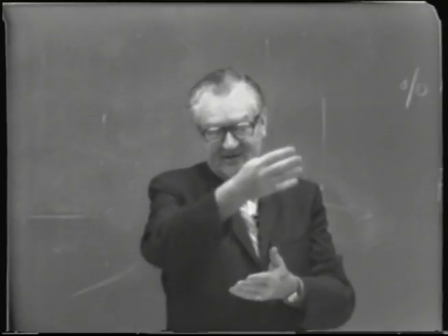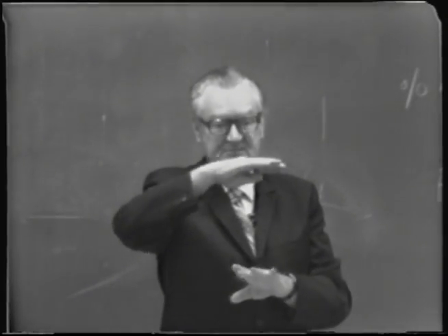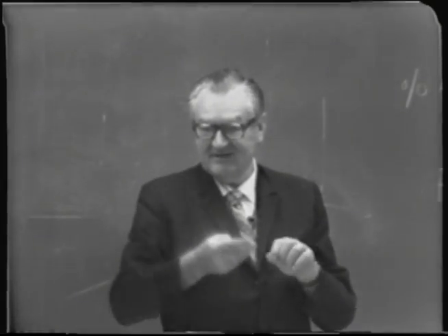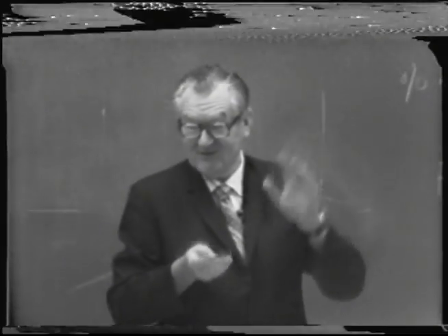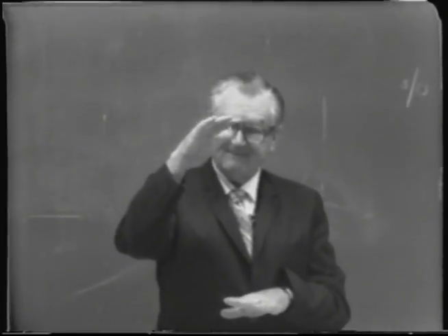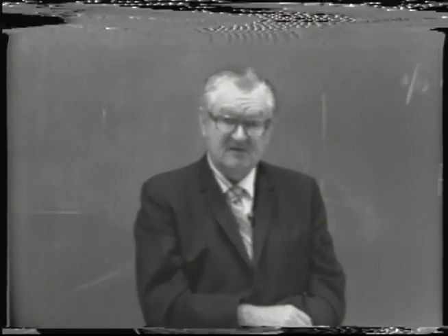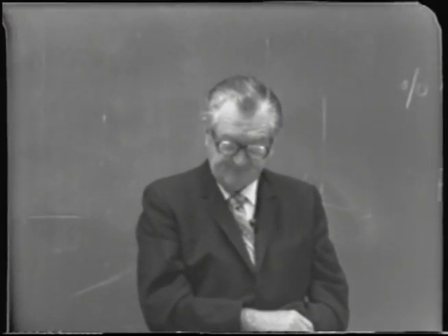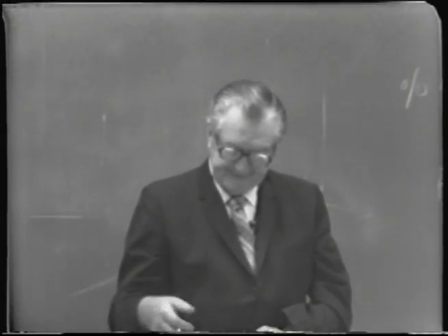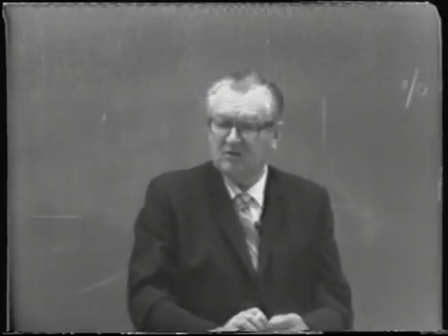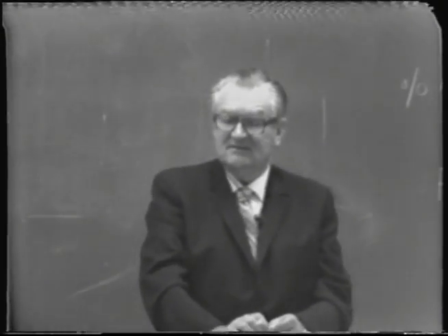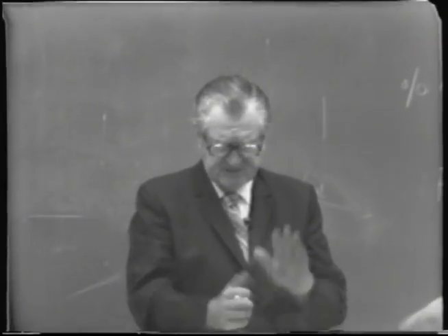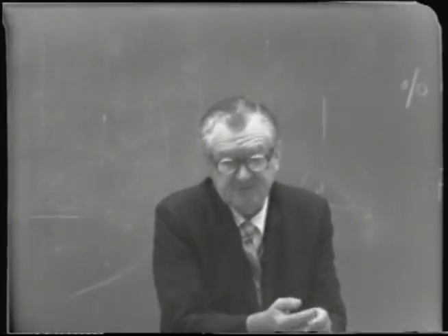If you mechanically carry up liquid from one tray to the next, you're defeating the objective, because you're tending to blend or mix two streams, and the purpose is to separate as far as concentration is concerned. So one of the aspects of determining plate spacing is that which will enable you to have an acceptable level of entrainment. There's always a little bit that goes on. And therefore, if you have a larger plate spacing, you have a higher vapor velocity without getting significant entrainment.